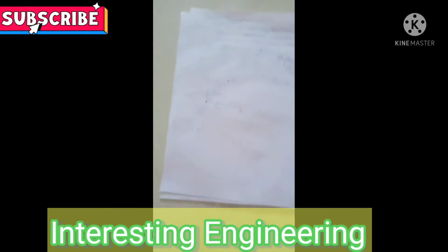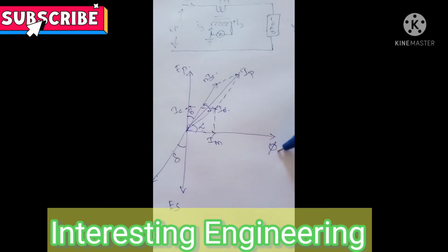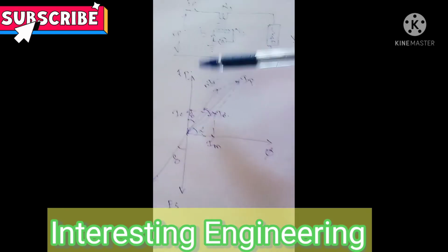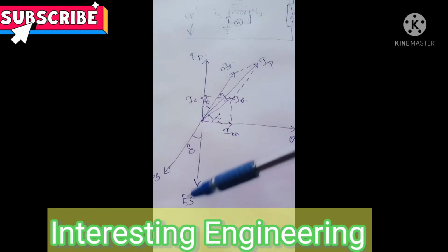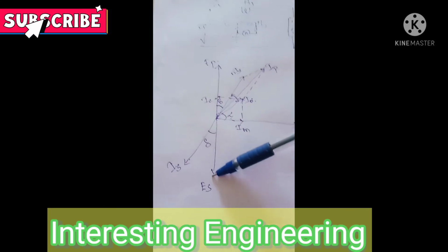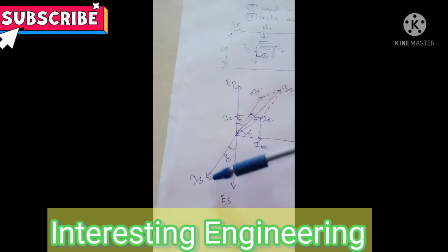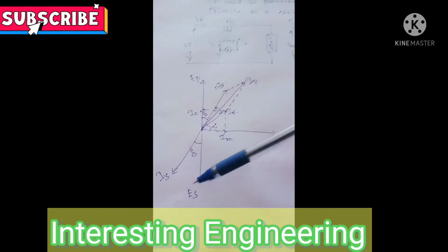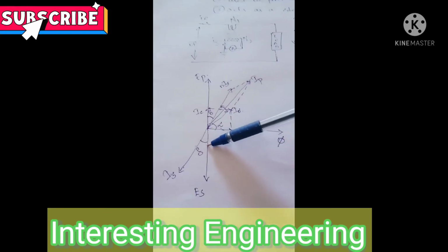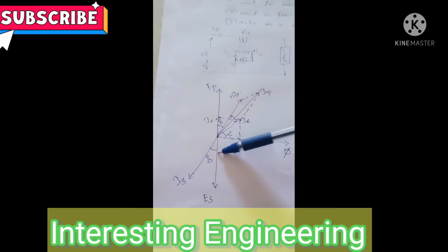So look at our phasor diagram. In our phasor diagram, we have represented flux, and due to this flux there develops EMF EP, and due to this EMF EP there develops potential ES, which is 180 degrees out of phase, and due to this ES there flows current. So this current will have a lagging power factor. So IS, I am representing it here with an angle of delta. So this IS due to IP is equal to NIS, I am representing here.